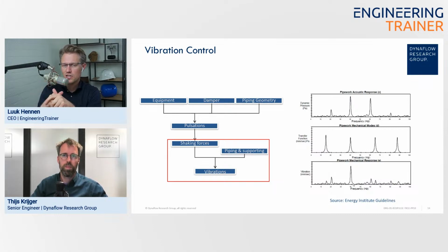Pulsations in themselves won't cause fatigue unless anything moves. Yeah, so it could be an issue if your pulsations are extraordinarily high, because the system will still respond even though you're not at a resonance. If you think of your simple mass on a spring, if your shaking force is large enough, even if it's off resonance, it'll still move.